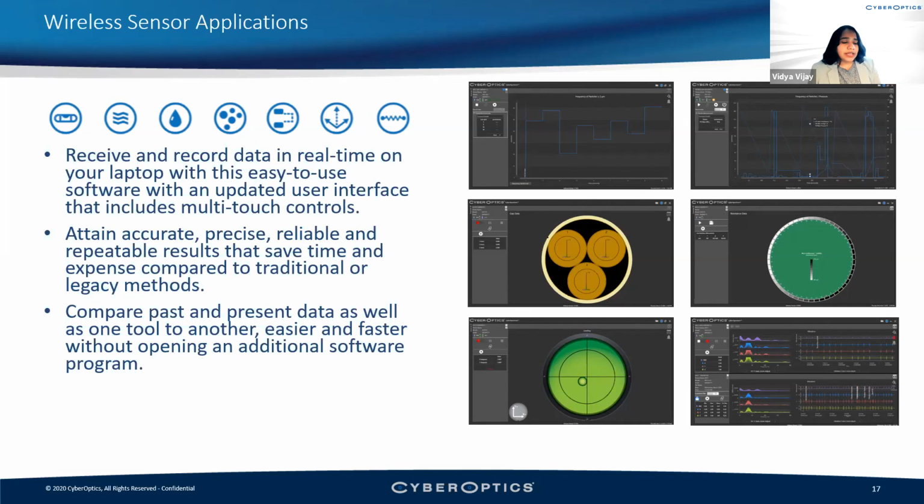We have this UI, very nice for different applications, but we also have something called a software development kit, because it is harder to customize it for different customers. We give them a library, and then they can say, if the vibration exceeds 0.5G, I would like a couple of engineers to be notified to go check, or to call for an alarm for immediate maintenance.